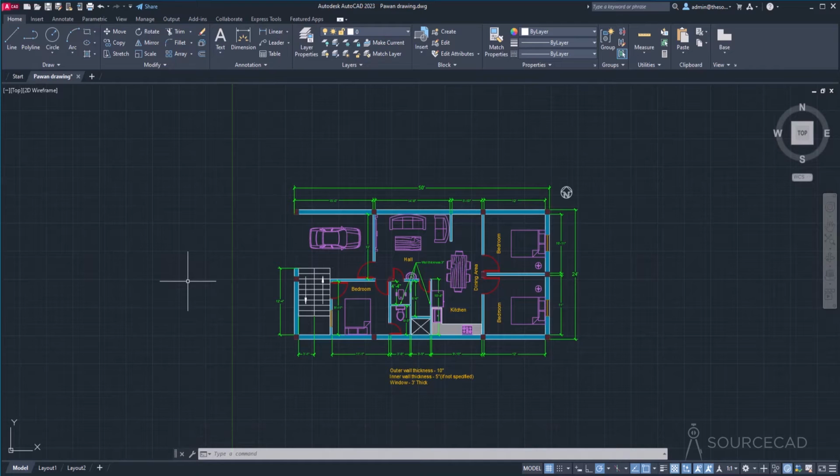Another one is dynamic input. Dynamic input is just this. On the status bar, you'll see this dynamic input right here. You can click it, and with that active, if you select a command, you're going to see this dynamic input dialog box right next to the cursor. Now this is something which people often want, and it's kind of like a personal preference thing. I don't prefer this dynamic input. I tend to keep it off. So if you don't want it, just keep it off, and this will also improve the performance.